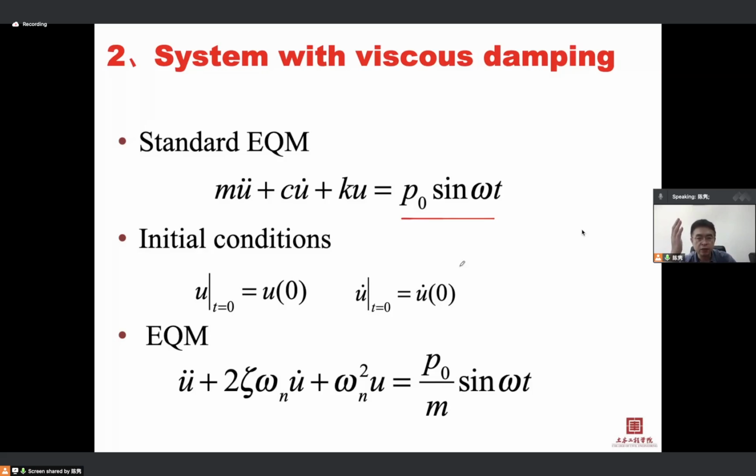If you design a structure whose period is nearly 1 second, it's dangerous. So you need to change the properties, the dimensions, or even the height of the structure, making the natural frequency or natural period of the structure be away from 1 second, which will be a safer design. Is that your question? Yeah. Thank you.